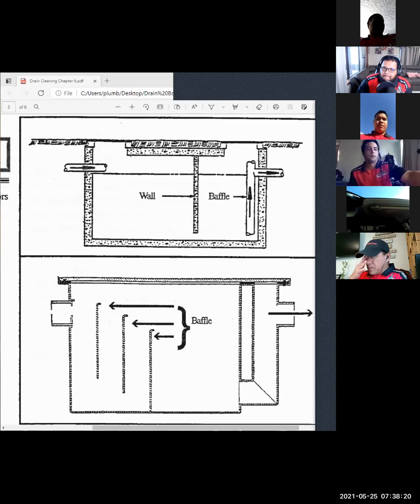It's real simple. If you guys think about a grease trap, very simple. What and where can the waste system collect grease from? So you got floor sinks, floor drains, rinse compartments, anything that they can get grease on. The reason they got the floor sinks is because they come off of other sinks. The floor drains, because you're washing the floor and there's grease on the floor, and so it can go in there. Hand wash sinks, it's really stupid, but there's no grease coming from a hand wash sink.